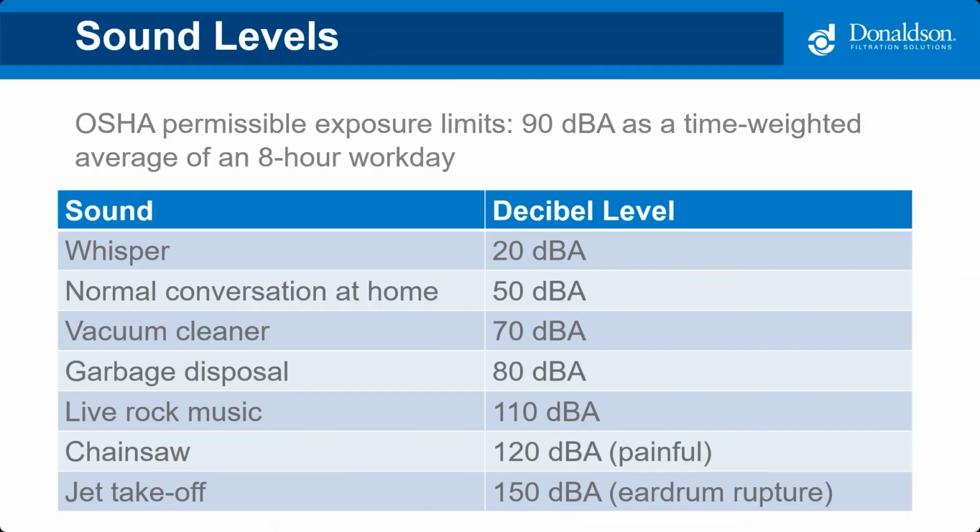OSHA's permissible exposure limit for sound is 90 decibels as a time-weighted average of an 8-hour workday. This is why many manufacturing facilities have programs in place to protect workers' hearing, and why I take sound into consideration when making a fan selection.